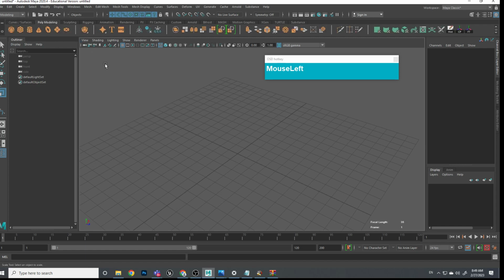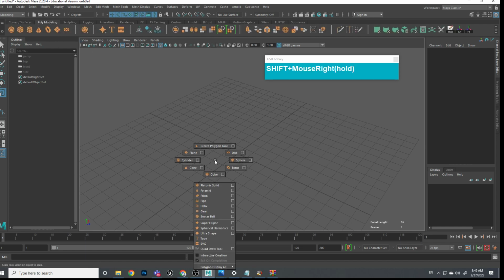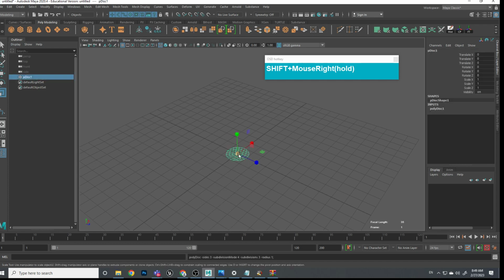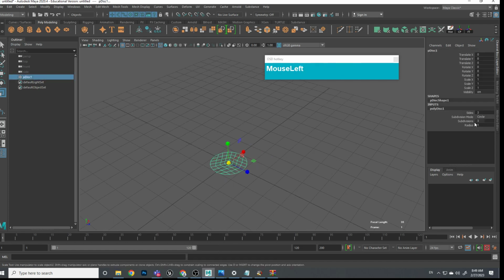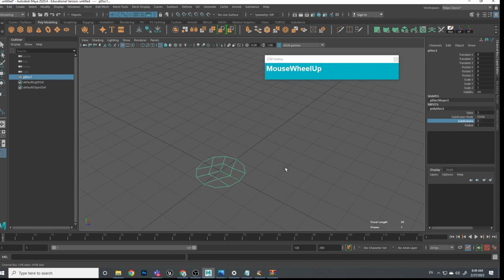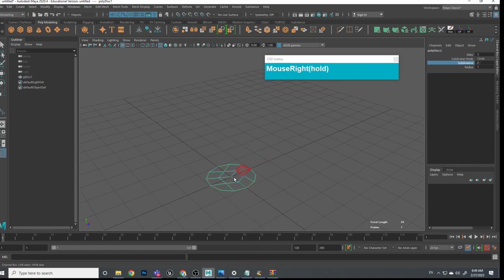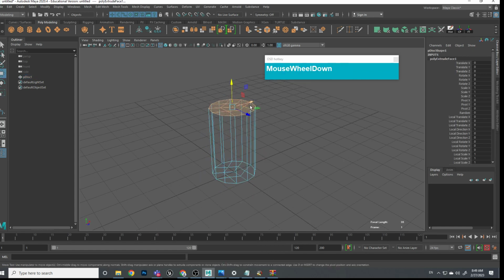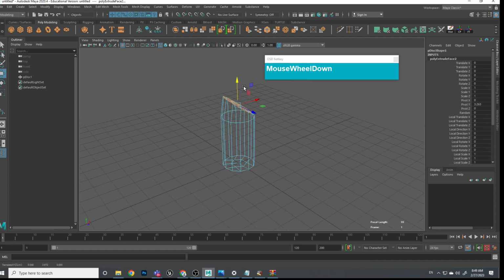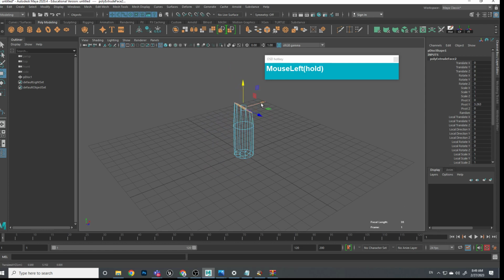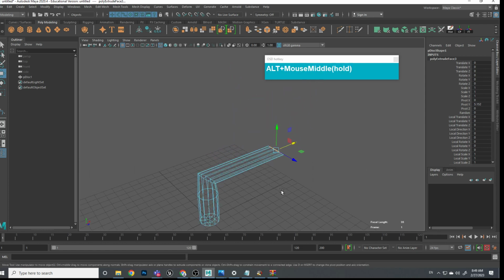So if you're doing a polygon, we can create a circular disc like that, and we're going to do a very low resolution disc, because we can subdivide this and get an equivalent shape. So we can select all the faces, then if we go to move, we can start to extrude, and then we can rotate, holding down shift at the same time, and extrude by moving the cubes.